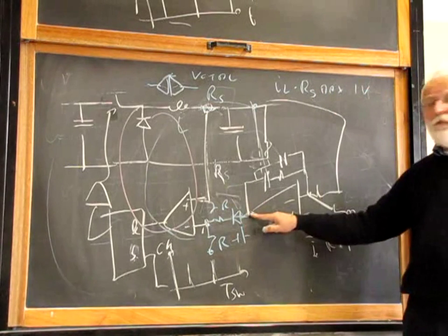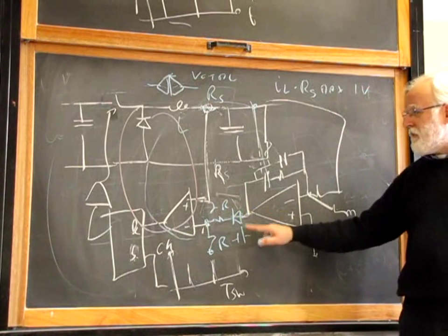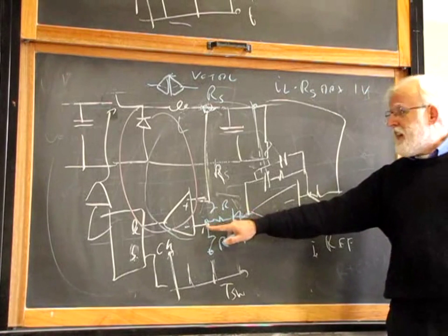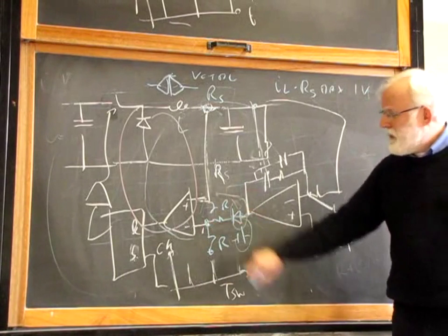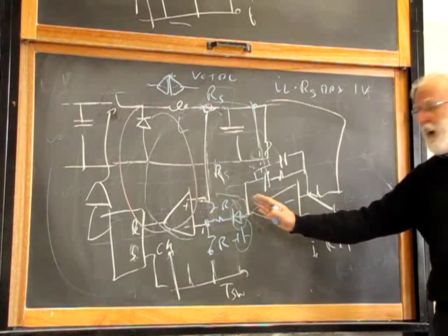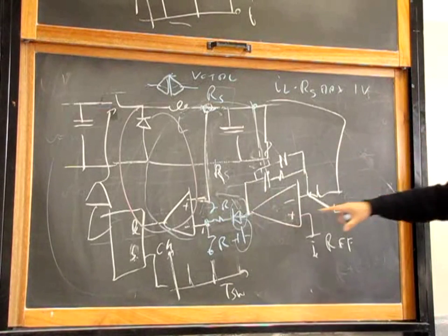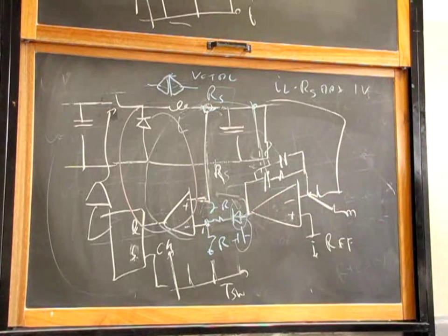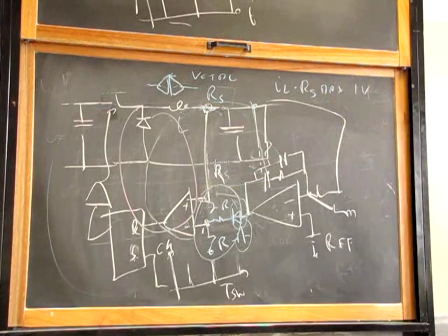And until the output voltage here reaches 0.7 volts at least, or 0.5 volts, whatever this battery is, it does not control, it does not ask for any current over here. This diode, this voltage shift offset, is not important because any DC offset after an integrator is just divided by the integrator DC gain, and so it has no effect on the output voltage. This voltage division reduces my loop gain by 10 dBs.